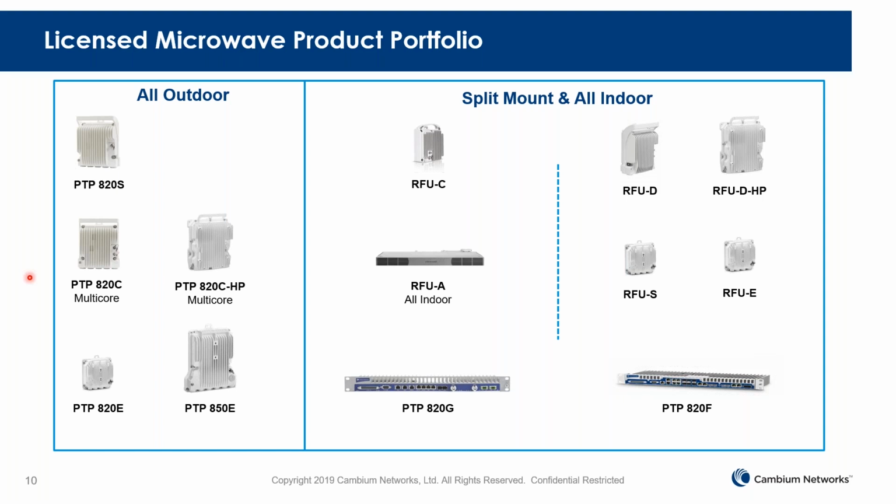That is the case, for example, in public safety, utility customers, oil and gas. Many of them still go with split mount, not only because they want to change the equipment easily indoors, but also because some of them still carry TDM like T1 or E1, so they want more interfaces. So our rule of thumb is if you're IP centric, go with full outdoor. If you still have TDM and other things, you go with split mount.